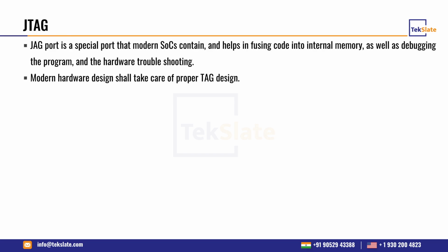JTAG design. The JTAG port is a special port that modern SoCs contain, and it helps in loading code into internal memory, as well as debugging the program and troubleshooting the hardware. So modern hardware design shall take care of proper JTAG design, which involves connecting the JTAG pins of the microcontroller to the in-circuit emulator. Any in-circuit emulator is typically connected to the JTAG port, and through the in-circuit emulator, one would download the program and so on. So this JTAG design is an important aspect of the microcontroller design.